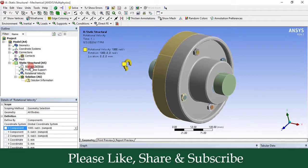Now I have applied the rotational velocity, I have applied the frictionless support to both the ends of shaft on the cylindrical surface. Now I want to constrain the displacement of this model along the x axis, because there is a possibility of displacement of this model along x axis, so we have to restrict it.